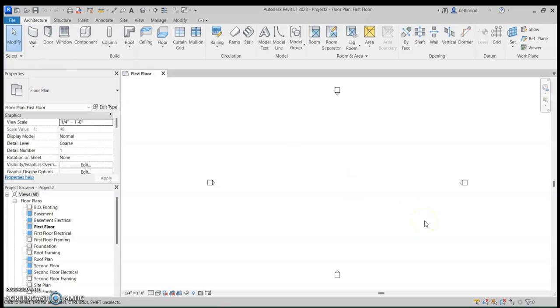Use the modify button. The next thing you want to remember is to always keep your model here within these 4 elevation markers. So these 4 elevation markers are there by default, and you want to keep them there. They are your actual exterior elevation markers. So we want to begin modeling here, kind of in the center of these 4 elevation markers that you see. The next thing to remember is that Revit defaults to feet and not inches.